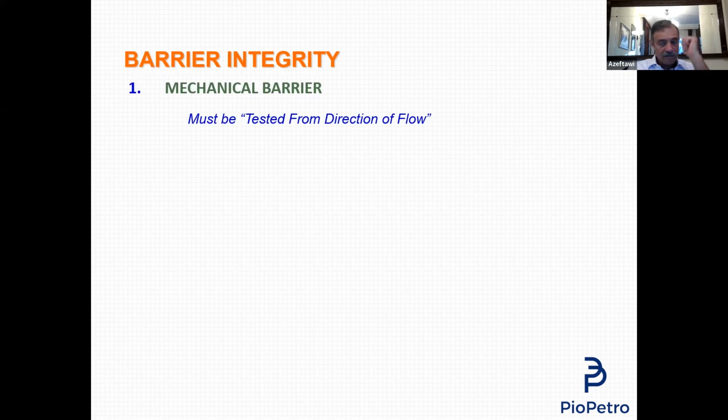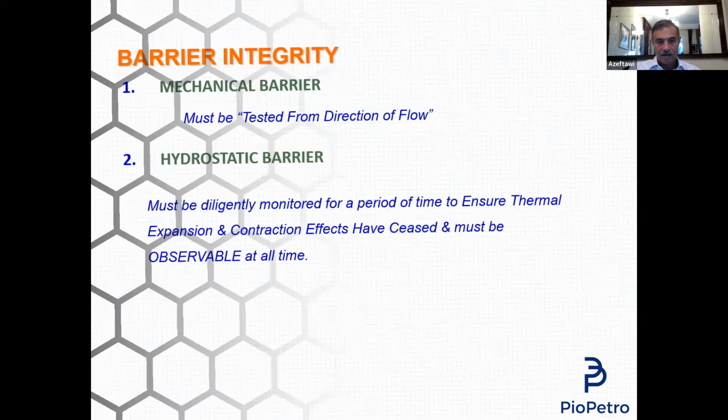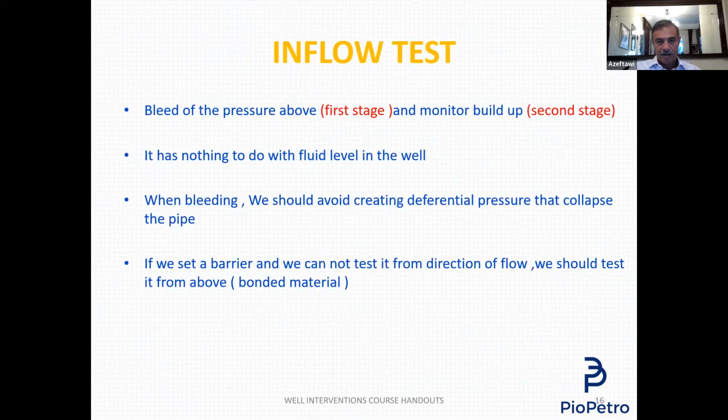Talk about the valves, either fully open or fully closed. Pressure control equipment, use it from the direction of flow to hold the pressure, not from any other direction. Okay, we said that when we test a barrier, we test it from the direction of flow.